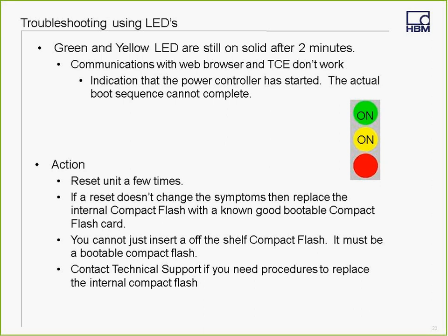However, like with any computer, we always want to try to power reset the unit a few times before troubleshooting further. If a reset doesn't change the symptoms, then replace the internal compact flash with a known good bootable compact flash card. You cannot just insert an off-the-shelf compact flash. It must be a bootable compact flash. Contact technical support if you need procedures to replace the internal compact flash.